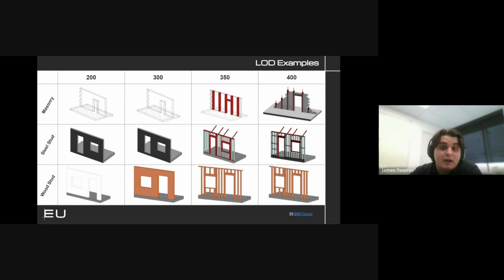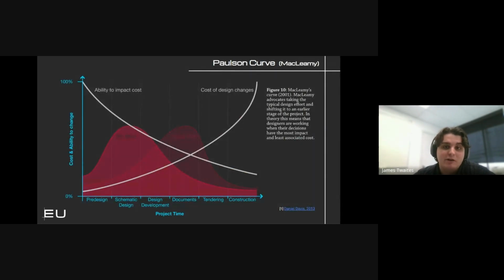In Vancouver, it's unusual for framing trades to be involved in BIM. So if you're looking for issues with header beams or stud packs, that information just won't be available until you get shop drawings, at which point someone would still have to update the architectural model to include that information in the BIM. And what that means is that there are types of clashes that can't automatically be detected. And even if they are, it'll come much later in the process. So if that kind of coordination is important for managing risks on your project, it's important to consider how that will be accounted for, how that data will get into the environment where you can use it.